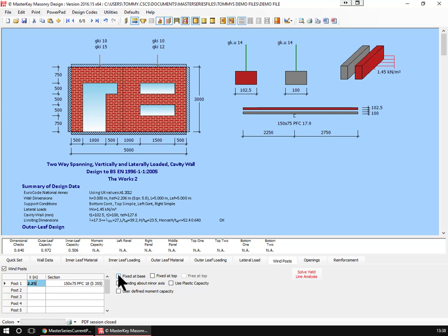Now, base, we could say the base of the panel was fixed and the top was fixed, or even the top was free. Obviously, again, for your freestanding walls, or where you're not able to get a fixity up here for whatever reason. We can also take the channel. The channel is shown on the outside surface, but naturally you would quite frequently put it in, divide the two walls up, and shot fix either side with ties to actually embed it into the wall, and you'd probably just hide it all together and skim over the top.